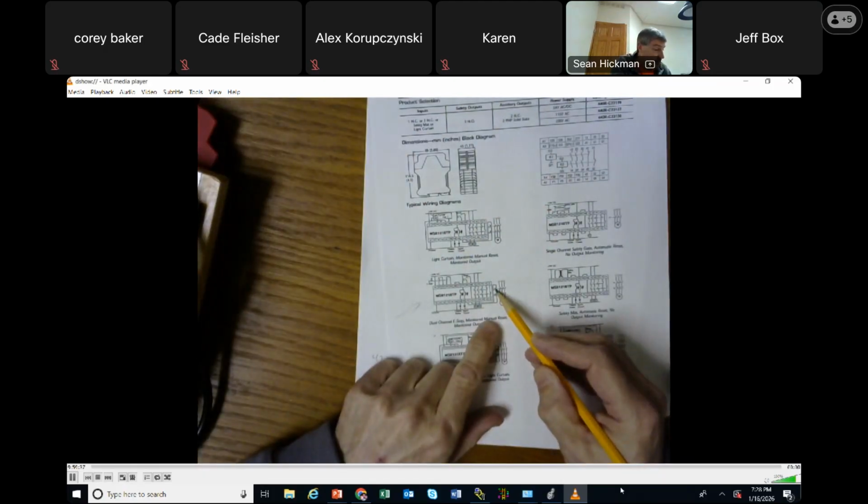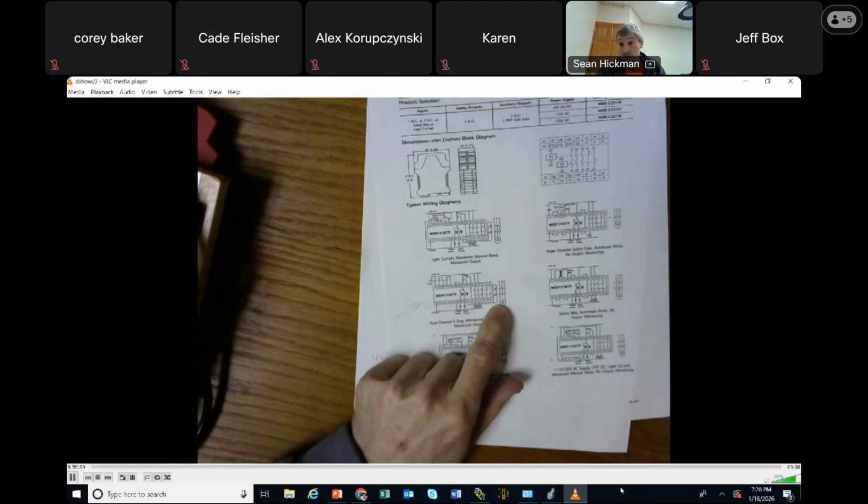And that's what this K1 is. K1 is a contactor. Now we're doing dual channel safety. So why start a motor with 1 contactor when you can start a motor with 2 contactors? I mean, what are the odds of a contactor failing? And it can fail. What are the odds of 2 parallel contactors failing at the same time? A lot lower.